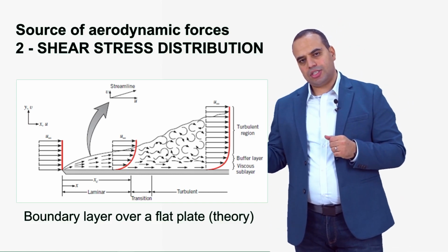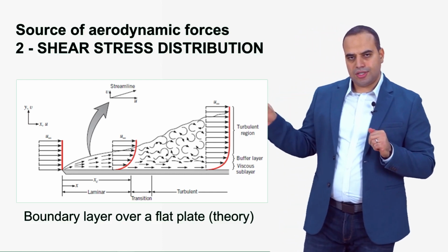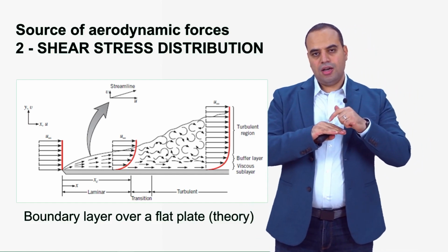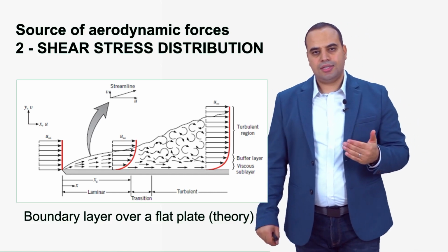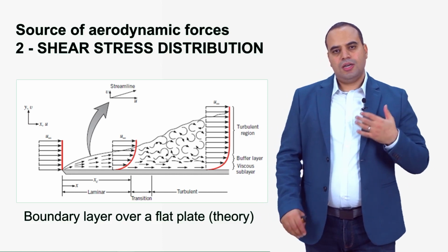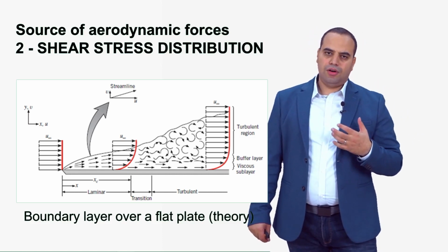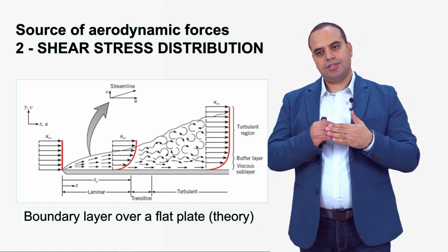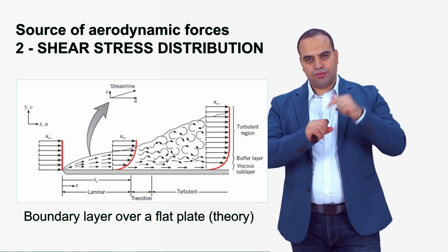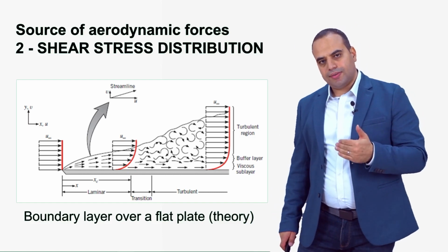So it means that these vectors are the velocity vectors, right? The smaller the vector, the smaller the velocity, and you can see that on the surface itself, the velocity is 0, which means that on the surface the gas stops moving. And why is that the case? Because this is a solid object, and it has a certain resistance to moving the gas. This resistance leads to stopping the motion of the gas. No matter how fast the gas is moving, on the surface itself there is always going to be zero velocity, and this is because of the viscosity of the fluid.